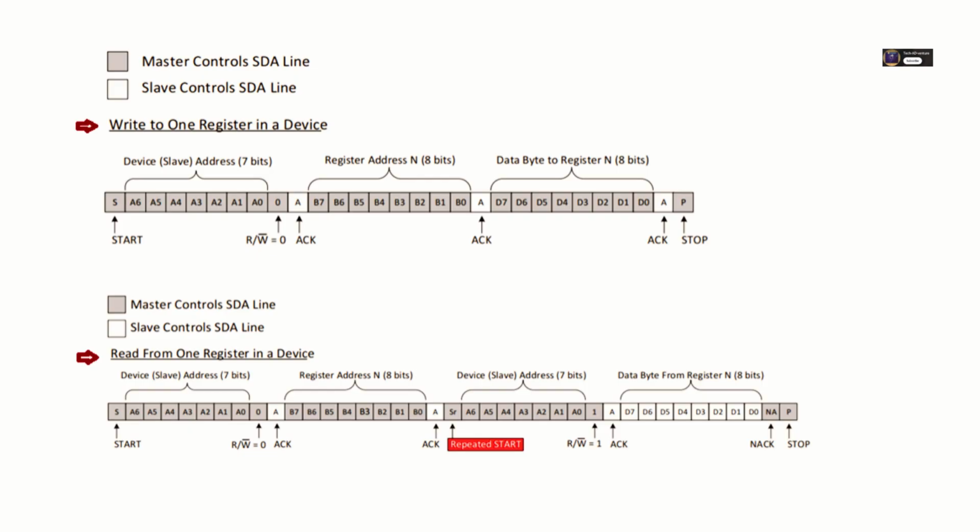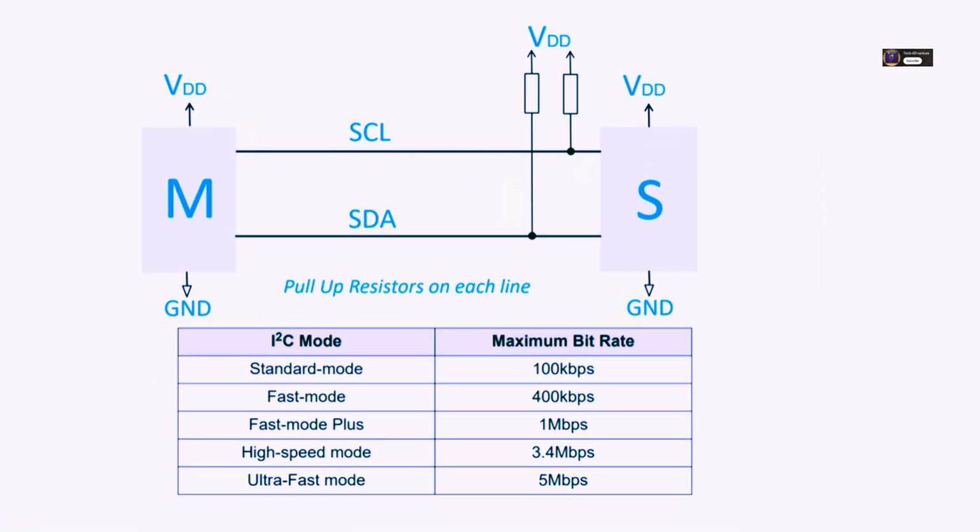So we've covered the logical flow. What about the rhythm, the speed, and how does it manage traffic, especially if things get busy? Right, the rhythm. I²C isn't just one speed. It has defined speed modes offering flexibility. The baseline is standard mode at 100 kilobits per second, kbps. Then you have fast mode at 400 kbps, which is very common these days.